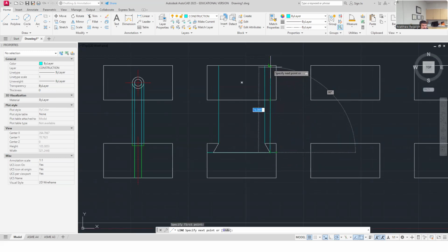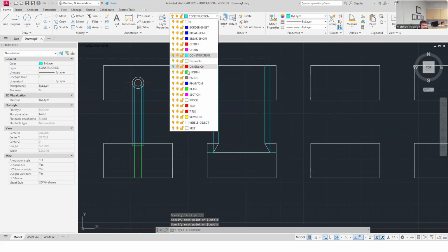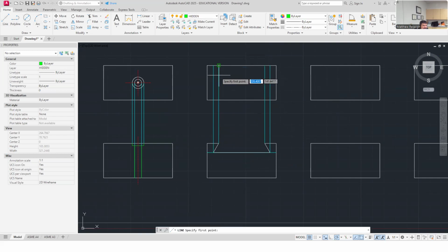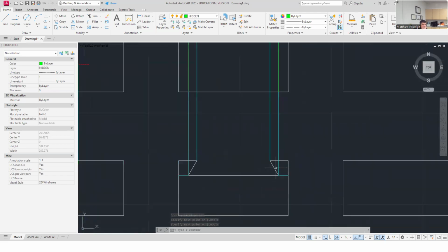This one is going to become hidden line work because I just don't have the X-ray vision to see that, even though it's down in there 8 millimeters deep. And my eyeballs are not on that surface, so I can't see it. But if I use some hidden line work, I can communicate that a little more effectively to someone else if I trace over it with my hidden line right there. And that one should be done, yeah? This one right here.